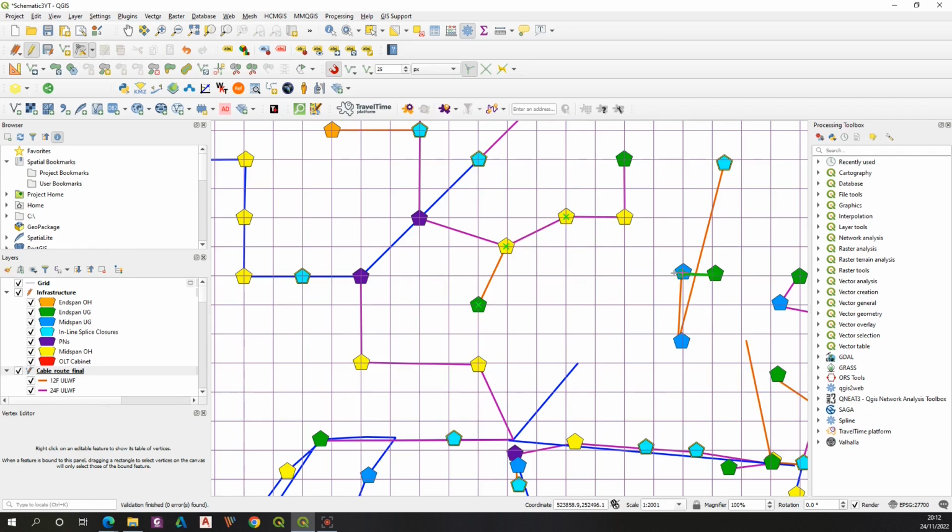In order to avoid a situation such as this, let me show you on an example. Imagine that I would like to change this position from here to there. I can't, because it's been snapped to another line, so I can simply change it by decreasing the number here, which can be 5 or even 4, 3, something like this. Then I could make my changes without a problem, like you see already.